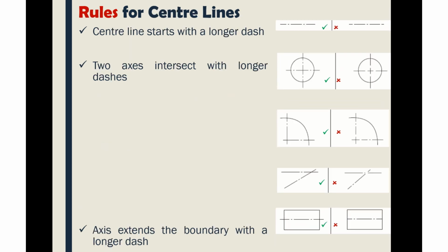Okay, let's look at the rules for center lines. A center line starts with a long dash, not a short dash. You start a center line with a long dash and not the short dash. Also, two axes intersect with longer dashes and not with the short dash. You can see the intersection here.